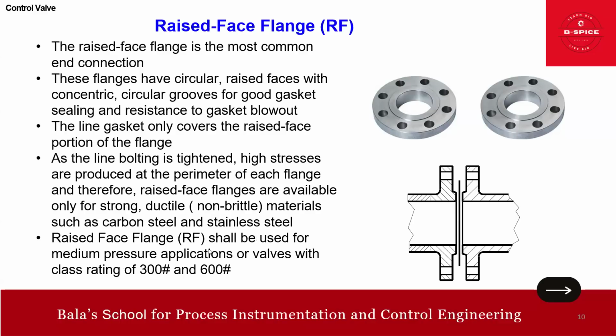Okay. So raised face shall be used for medium pressure applications or valves with a class rating of 300 and 600. Up to 600 we can go for this raised face. Okay. In some cases they go to 900 also, but for 900 we have some other types also. That is why I just limit this to 600. But it's not necessary that we should stop.